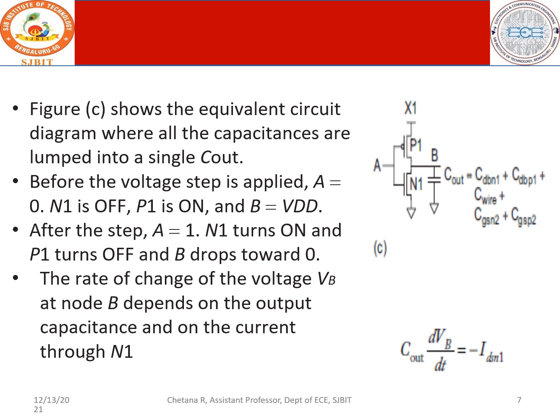And at the same time, when the voltage at node B is high, C is charged to the maximum. C is charged to VDD. When this is an open circuit and N1 is on, C has a path to discharge. So C discharges through this path, and the moment it is discharging, the voltage here happens to be 0.